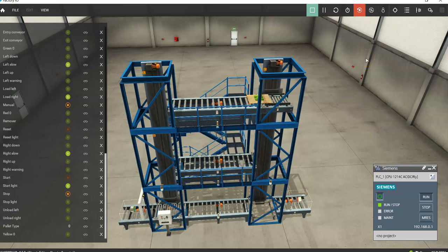If you want to, as they say, if you want to try this at home, maybe you can have them both go up at the same time, or try to get the timing a little better on the pulse that makes it go up. Okay, so that was one green. Here's the second green. Now this one will go up a lot faster because it's in full speed mode. So instead of starting to go slow right about here, it'll go slow right here. And that's kind of what you want to have. And again, you have to use the slow signal, otherwise you're going to overshoot this conveyor level. And there's no getting around that.